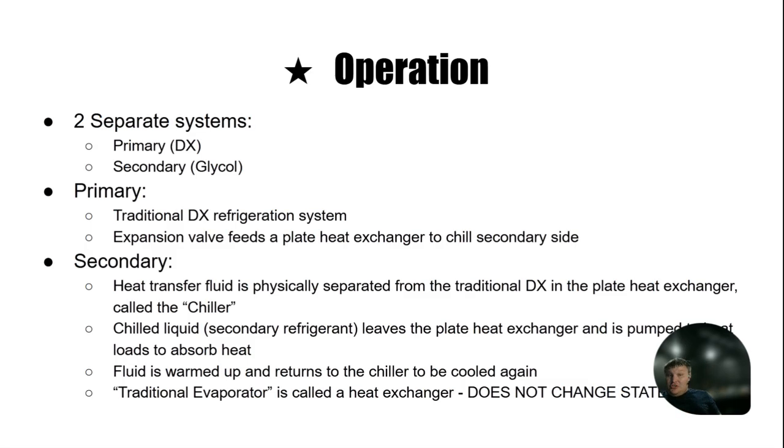Once that glycol is chilled, it is pumped around the store and picks up heat in the cases. Then inside of the cases, the traditional evaporator that we're typically seeing is a heat exchanger where sensible heat is the only way we transfer heat from air to glycol. There is no latent heat or phase change that occurs in the glycol. Glycol does not change state. That is a big deal here.